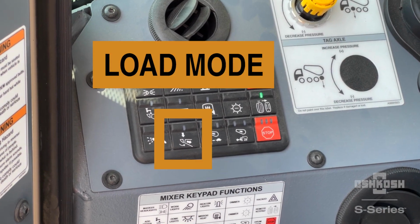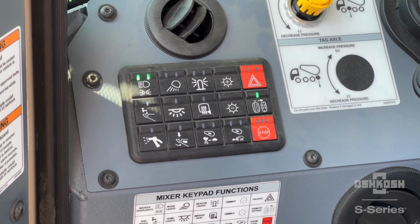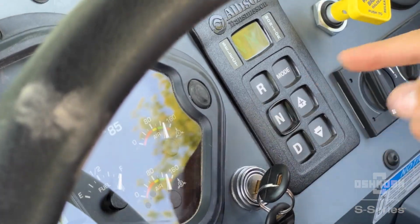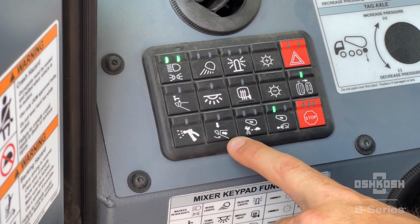Lastly, we'll talk about load mode. The primary use of load mode is to load material into the truck. To enable load mode, the same 3 interlocks as mix mode must be met. The parking brake is set, transmission is in neutral, and the service brake is not enabled. If these are met, press the load mode button once to activate.